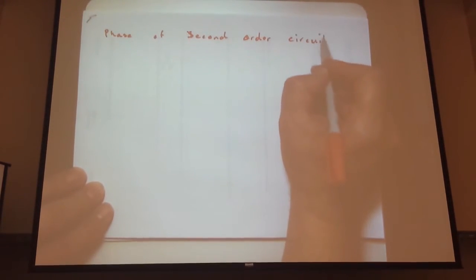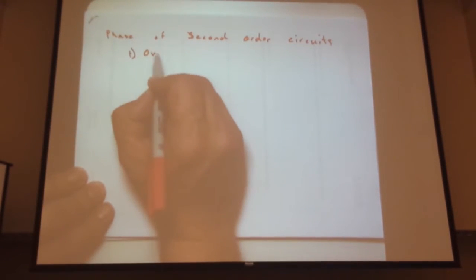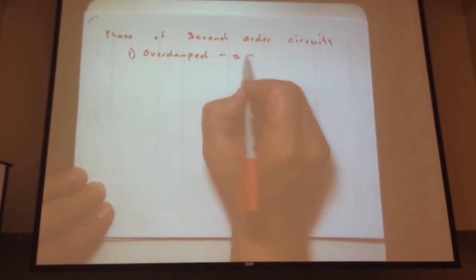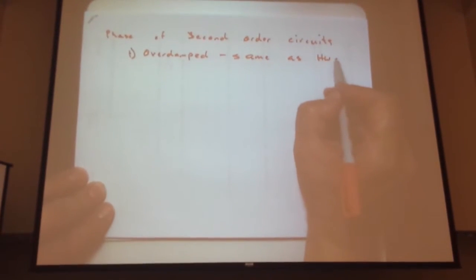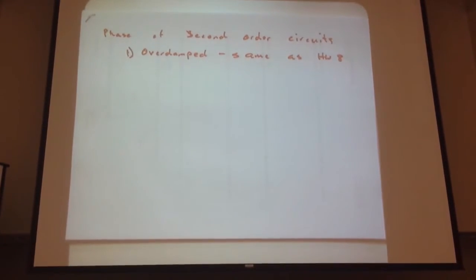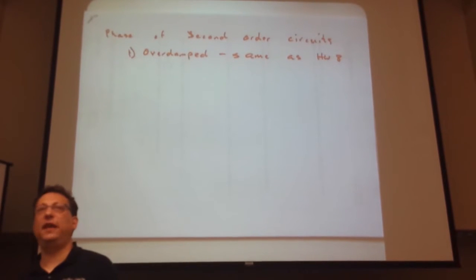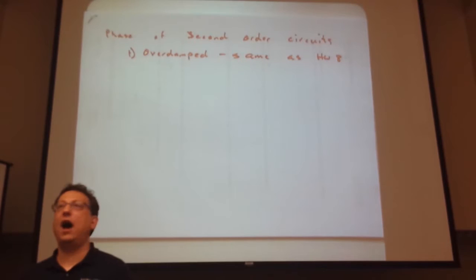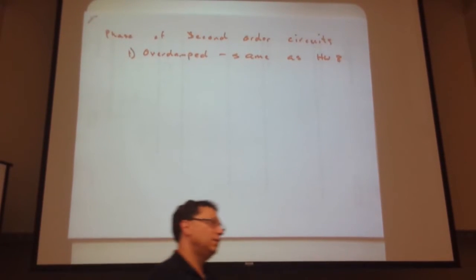And again, overdamped, same as homework 8. Find the poles, find the zeros, everything's real. You cross a pole, what happens to the phase? The phase changes by 90 degrees. Approximately how? Over 2 decades, one below, one above.